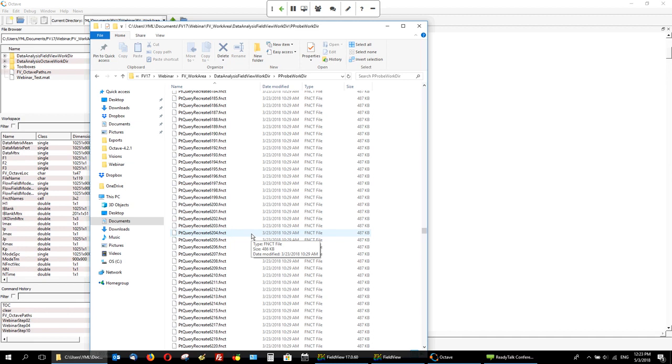All right, so these files, when I say reconstructions, what we've done is we already had the mesh, remember, from the resampling we've been doing. So we've been using the plot3D file format to write the reconstructed fields for velocity. So now that we have that in the plot3D format, we can load it back into FieldView.